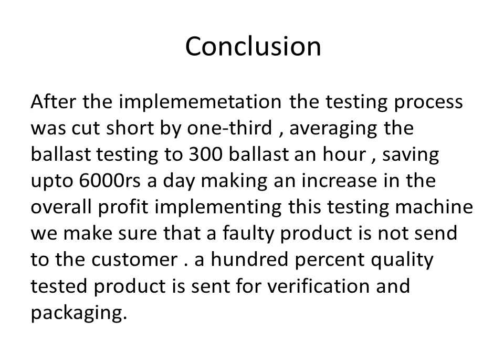Conclusion: after the implementation, the testing process was cut short by a third, averaging the ballast testing to 300 ballasts an hour, saving up to 600 rupees a day, making an increase in the overall profit. Implementing this testing machine, we make sure that a faulty product is not sent to the customer. A 100% quality tested product is sent for verification and packaging.